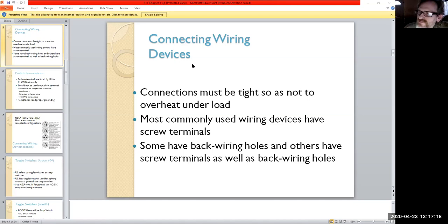Your wire strippers have a couple of different features on them. The main event is to strip different wiring sizes, and you can get them for different ranges too. They make the electronic style, where I literally had a set that went down to number 30 up to about 22, the really small stuff. And then you get the residential set, where it's number 10 down to 18, I think. Might be 22 on some of them.